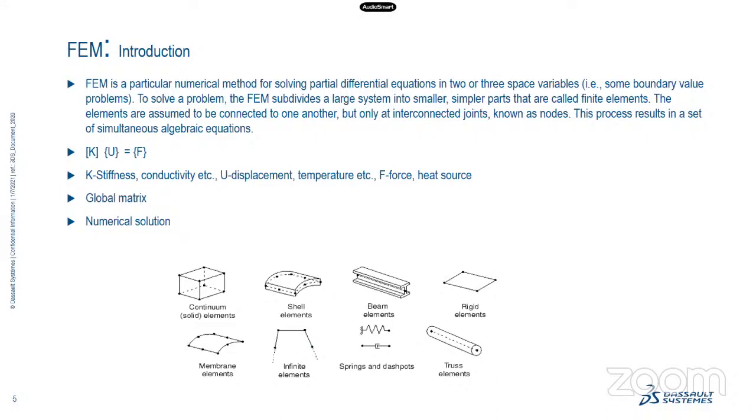We will have a basic stiffness matrix equation, like Ku = F, where K can be stiffness in structural analysis, conductivity in thermal analysis, and U is displacement, or temperature in thermal analysis. Basically, from the partial differential equation we make it algebraic, a system of equations.